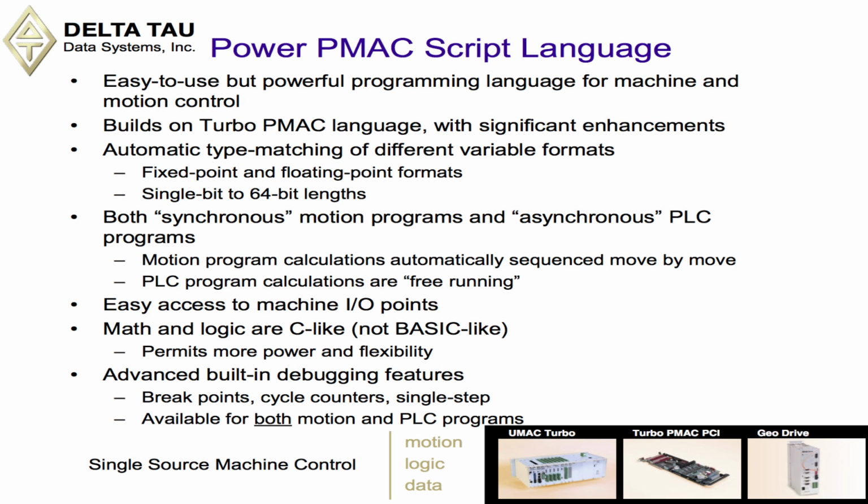The motion programs particularly, we call them synchronous. They're sequenced by the move. One of the things that commanding a move does is it takes a finite amount of time, rather than just, say, turning on an output where you just do it and it goes, but it may be a 10-second long move. In a standard high-level language, you at the application have to monitor for it to be over. And particularly when you have a sequence of moves together, you've got to be calculating ahead, and it gets to be very complicated. We've put that all under the hood, so you don't have to worry about it in our script language. The pipeline can get 7 stages deep, and it'd be tremendously difficult to do by yourself. So we sequence it move by move.